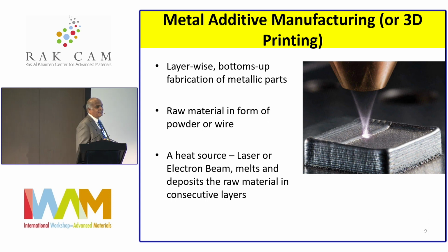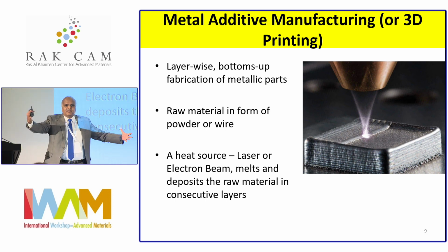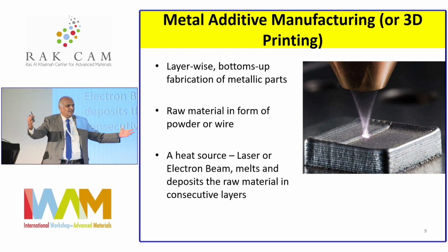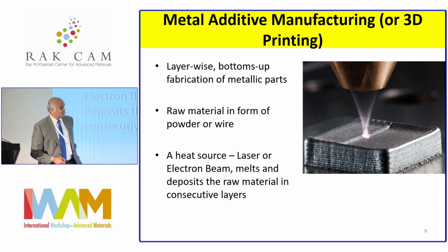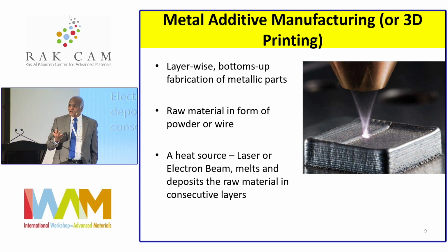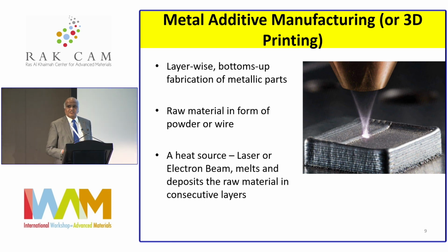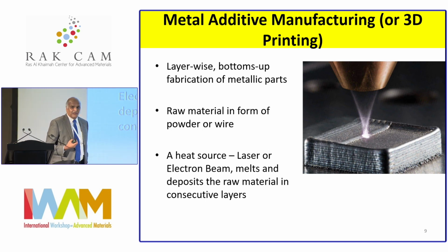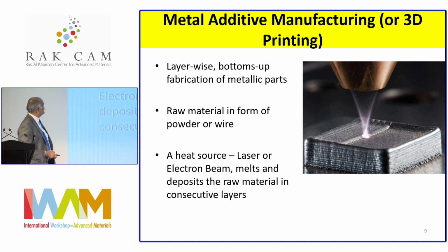Conventional manufacturing is often subtractive manufacturing. You make a big casting of something, then you beat it down to smaller sizes, and eventually machine it to get the part that you want. Whereas here, we mimic nature in some ways. We build bottoms up, right? In the metals context, the raw material you start with is powder, okay? And metal powders require sufficiently high thermal input, so we use lasers or E-beams to melt them, okay?